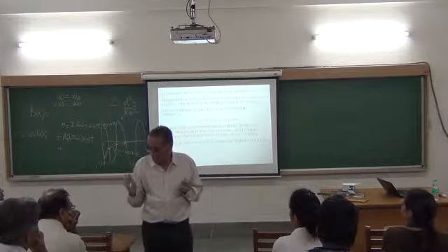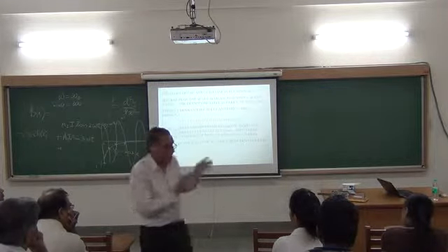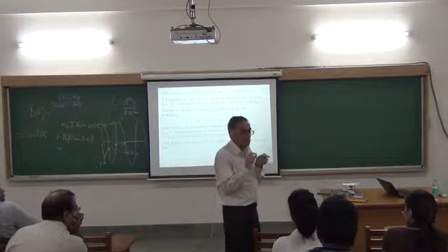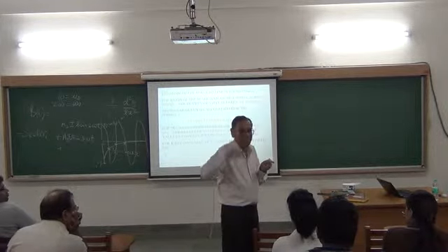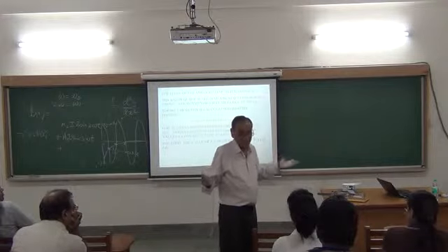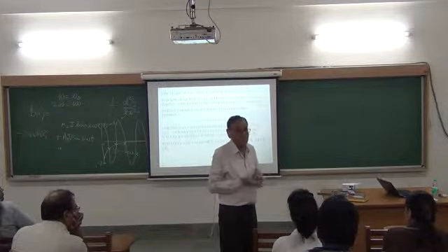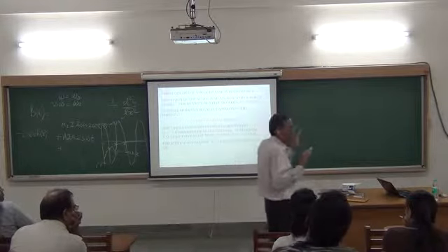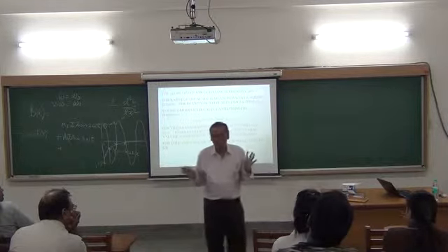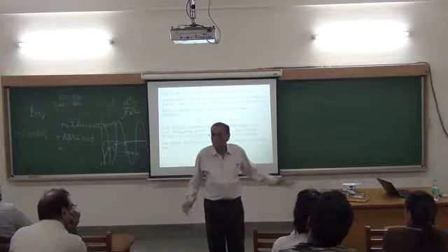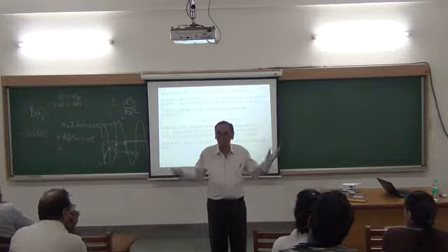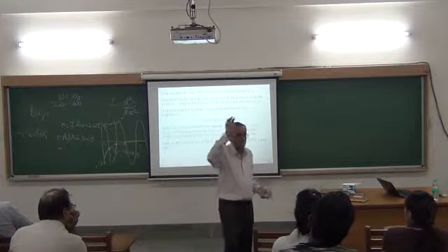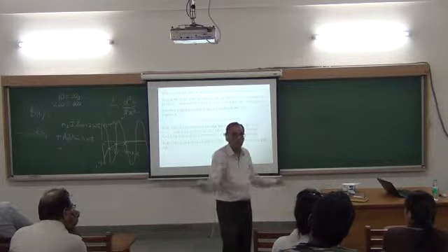To determine resonance is more complicated. But the principle is exactly the same. You change the frequency and find the new resonance. So this is the preferred method used in research and the most accurate method for measuring elastic constants. And it is a very easy method to do, because you only have to change the length, note the frequency, and keep the amplitude.